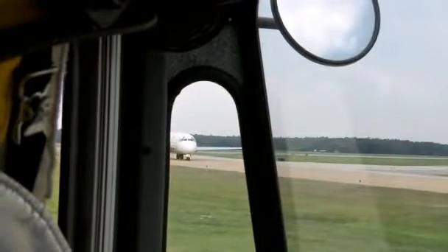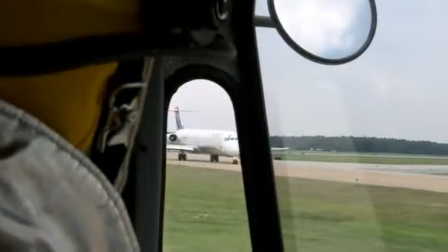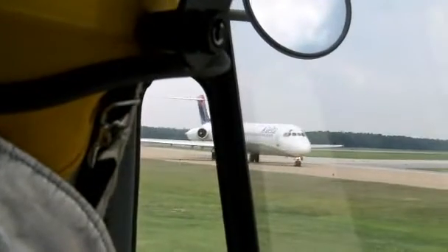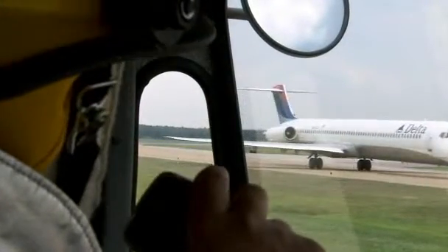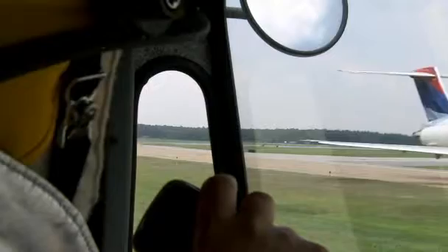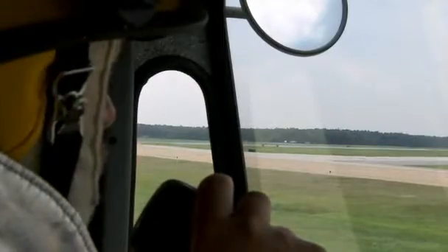ARFF personnel may also speak to pilots after landing to ask about the situation of the aircraft and its occupants, provide information on exterior conditions, request engine shutdown, or recommend an evacuation decision. The final decision to evacuate or not rests with the pilots. Always keep cockpit crews informed regarding what is going on, what you intend to do, and what you recommend they do.